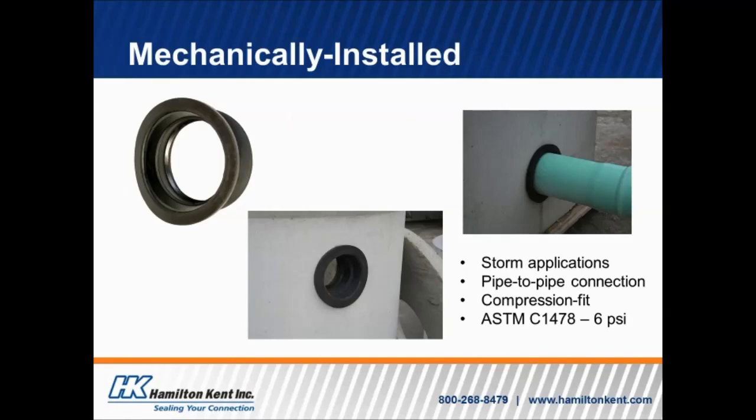And then on the right-hand side, as that pipe has gone in, it's a little bit bigger than the actual connector itself, and so it puts a little bit of outward pressure on that connector, thus creating an even tighter fit with the concrete structure. So it is a good compression fit type of connection. Meets ASTM C1478, which is up to 6 psi of water pressure. So it's a good soil tight type of connector, easy to install in the plant and easy to use in the field.